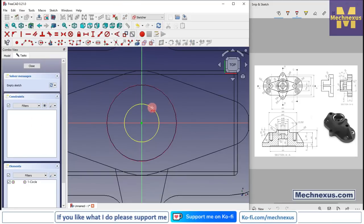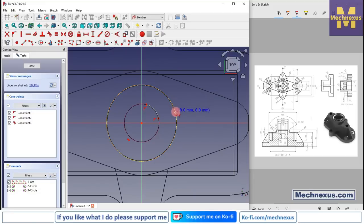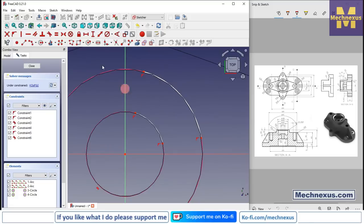We will project these two diameters, and we will select arc tool and create a 3-point arc, and select line tool, line, and line, select this and provide the horizontal, and select this, provide it a vertical.